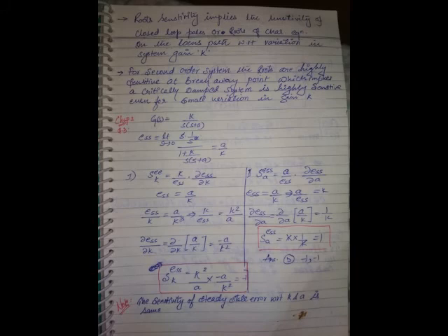So construct the characteristic equation: 80 into (1 plus TdS) by (s square plus 8s plus 80) equal to 0. s square plus (8 plus 80 Td) s plus 160 equal to 0. Omega n value is root 160, 12.64. 2 zeta into 12.64 is 8 plus 80 Td.